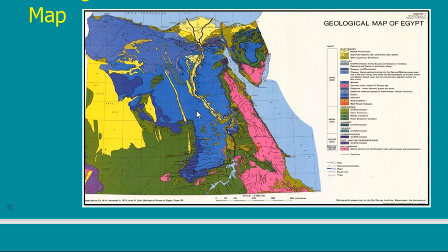When I know what I expect to find, then I can do a site investigation. If I go there and do boreholes, and these boreholes are in accurate confirmation with the geologic map, then I don't need to make other boreholes.